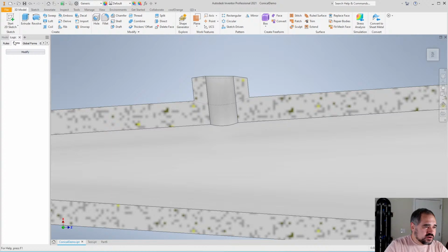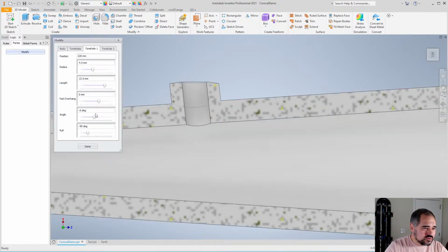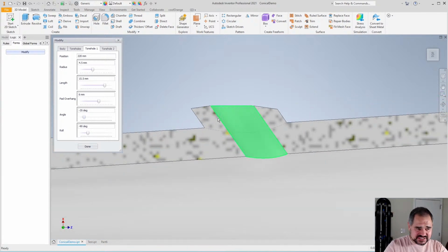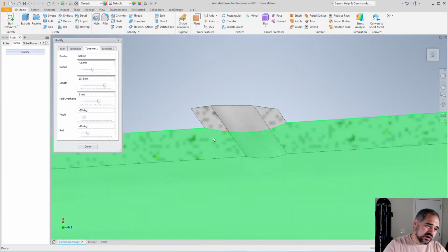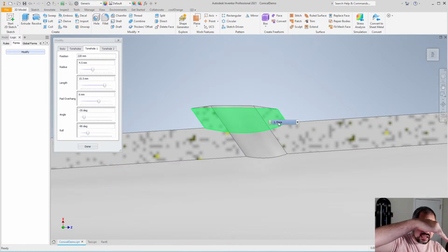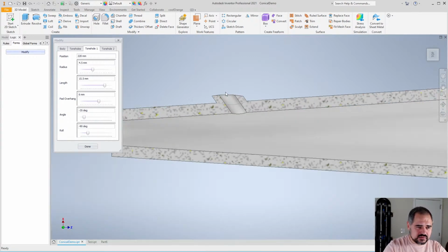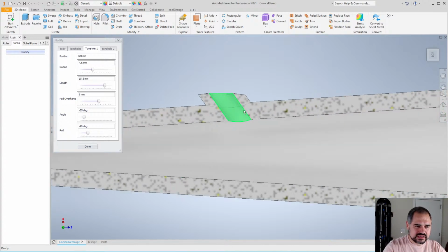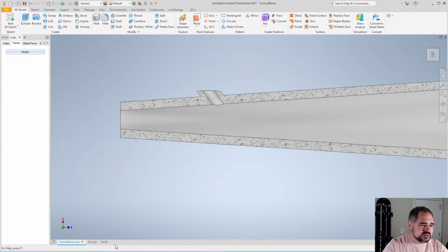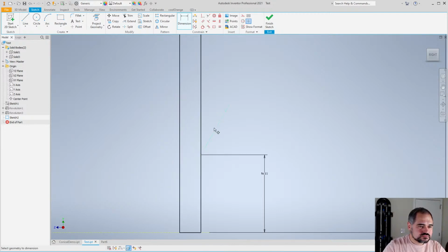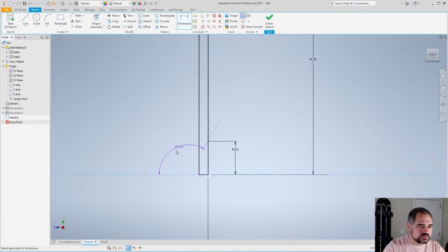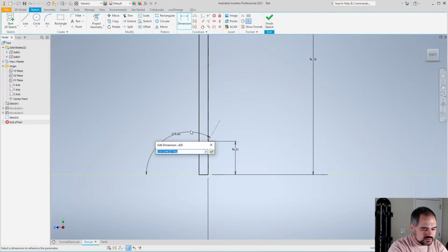So you might notice here, when we angle the tone hole, we normally wouldn't want to angle the facing, right? You wouldn't want the pad to have to come in at some weird angle to match the angle of the tone hole. You want the pad to be perpendicular to the body of the instrument. So in order to do that, we are going to set this angle at our tone hole.